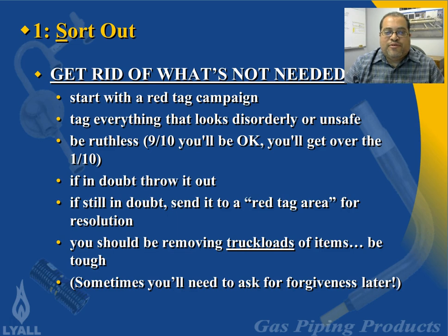And you're going to go in with this strict definition of value-added and non-value-added. Whatever's non-value-added, you're going to red tag it. You may not be ready to dispose of it yet, but you're going to flag it for disposal. So you tag everything that looks disorderly or unsafe, especially. But beyond that, anything that you can't see adds value, like right now or very soon.